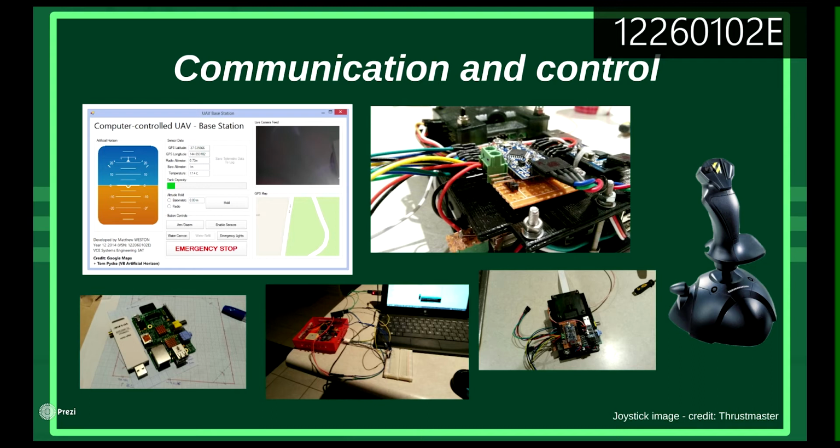There is scope to use a mobile data network for the communications link, which could allow for greater range. The computer control software was written in Visual Basic 2013, and communication occurs via the HTTP protocol. On board the vehicle, there is a Raspberry Pi computer coupled with an Arduino control circuit. The Raspberry Pi is running code written in Python, and Arduinos use a C-based language. I have created custom circuit boards to control the various lights and mechanisms on the vehicle. The drivetrain is controlled via a commercial flight controller which receives data from the Arduino circuit.